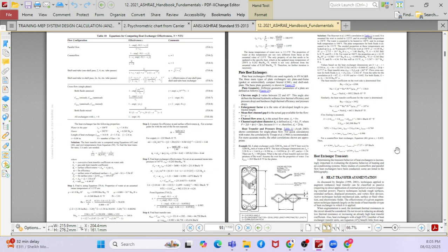But when we are choosing 4, it is because 4 is the highest efficiency, right? So once we advise 2.8 after our calculation, we send to the manufacturers, and we will select the higher one. When you prepare the equipment schedule for the chiller, you will prepare your motor power based on 2.8. But after you send to the manufacturers, you will get different values. So you will compare the manufacturers and choose the best one, and based on the best one, you will modify your equipment schedule. Clear?